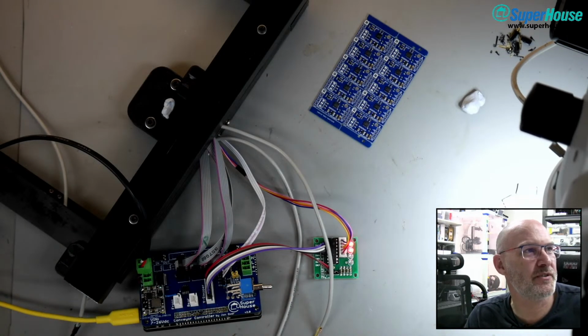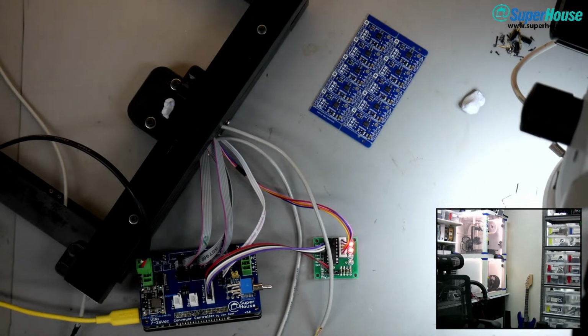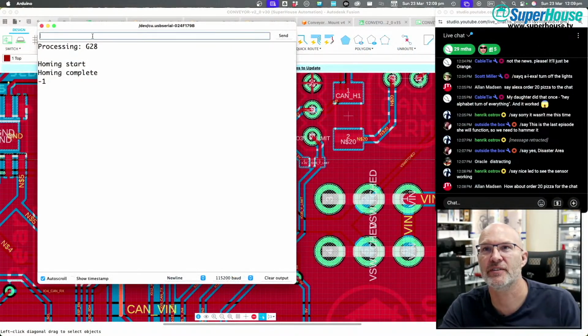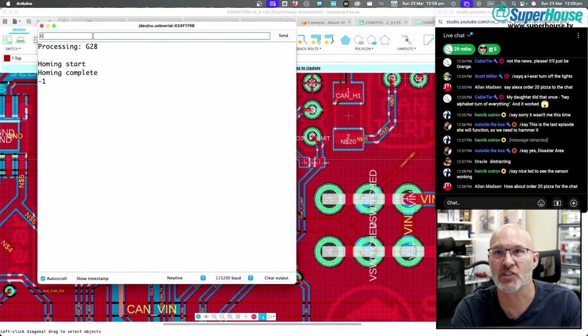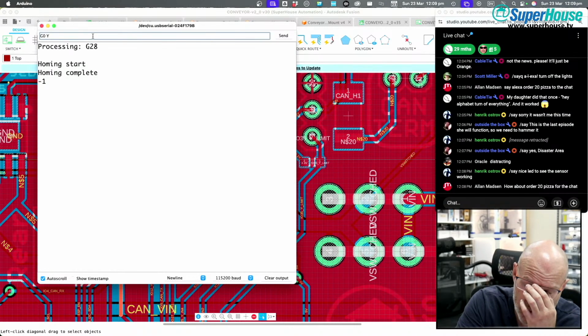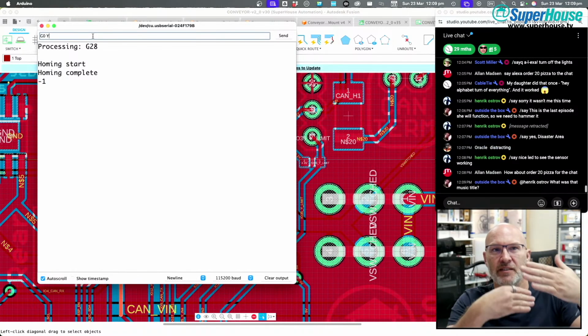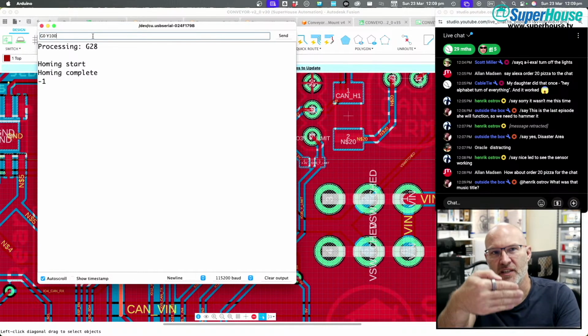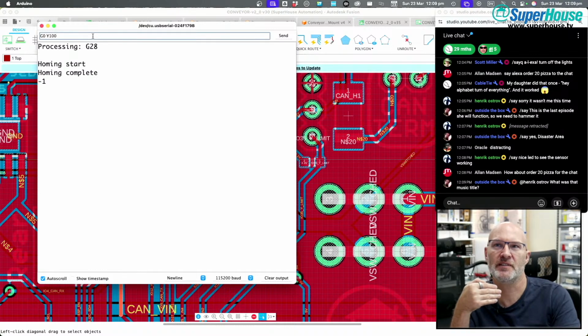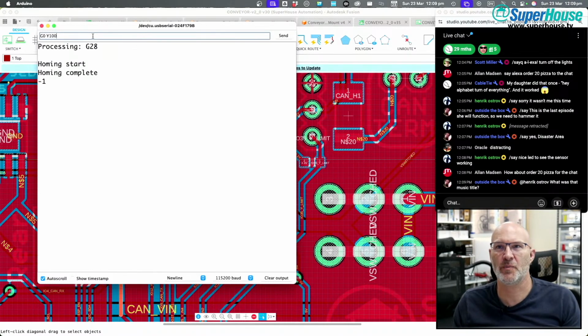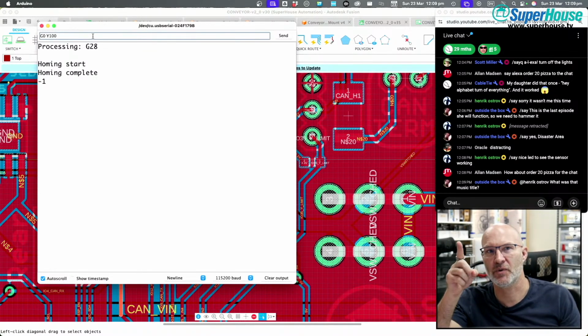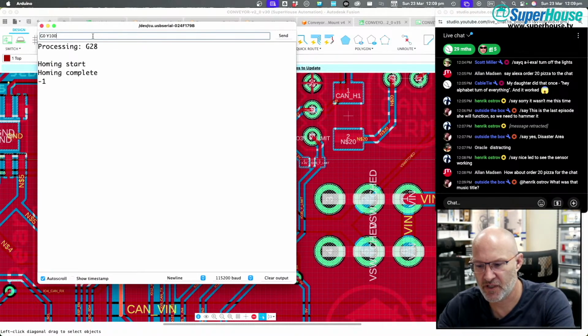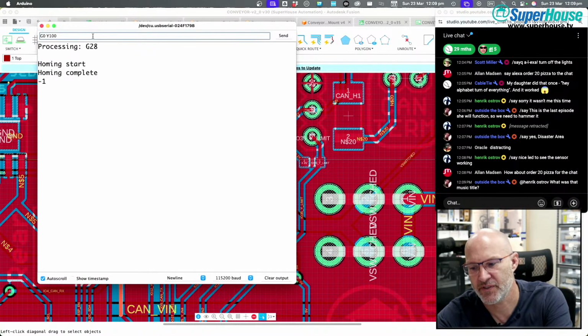So what I'm going to do is send a command like G0. So this is go on the Y-axis, and I want to set it so that the PCB width, like the conveyor width, is 100 millimeters. So what it should now do is try to move the rail forward until it stops at the 100 millimeter point. I'm going to hit go on this, switch the camera view, and we'll watch it turn, and then it should stop after a certain period of time.